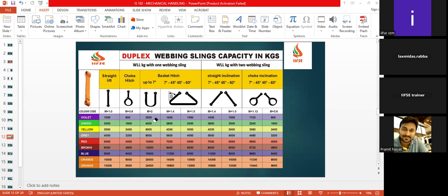That is also a strong point we have to communicate to the workers. It does not mean that you can lift up to 2000. Here it means that the belt has a capacity to lift up to 2 ton, but we are supposed to lift only 1 ton.